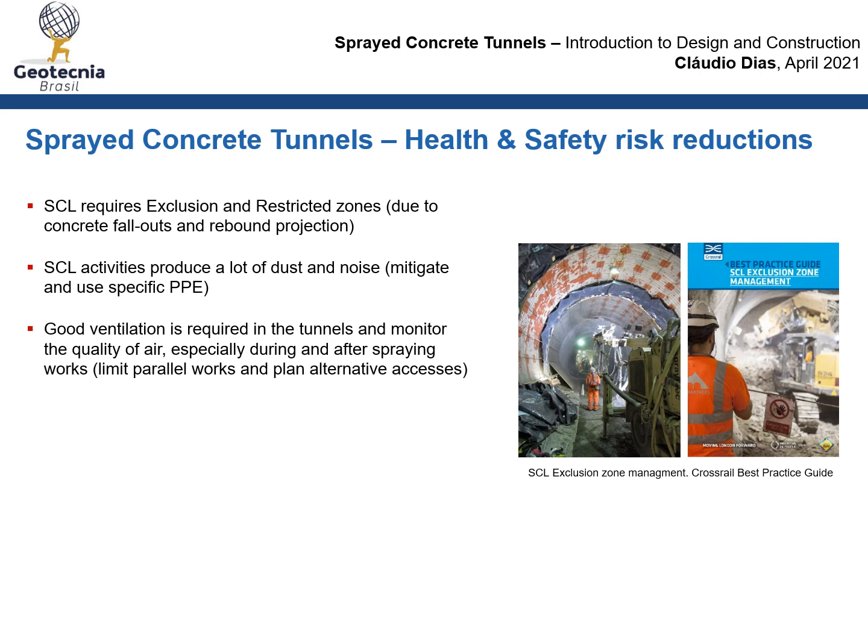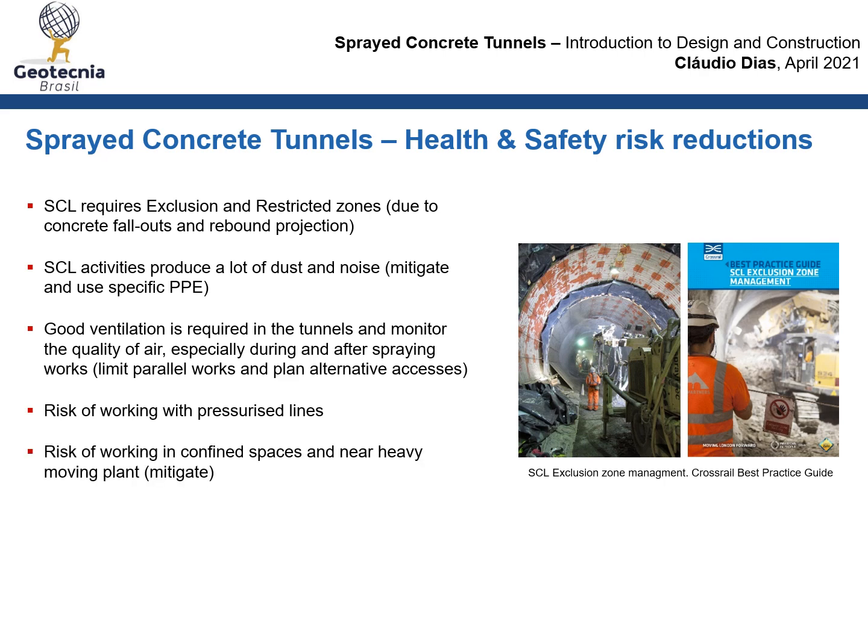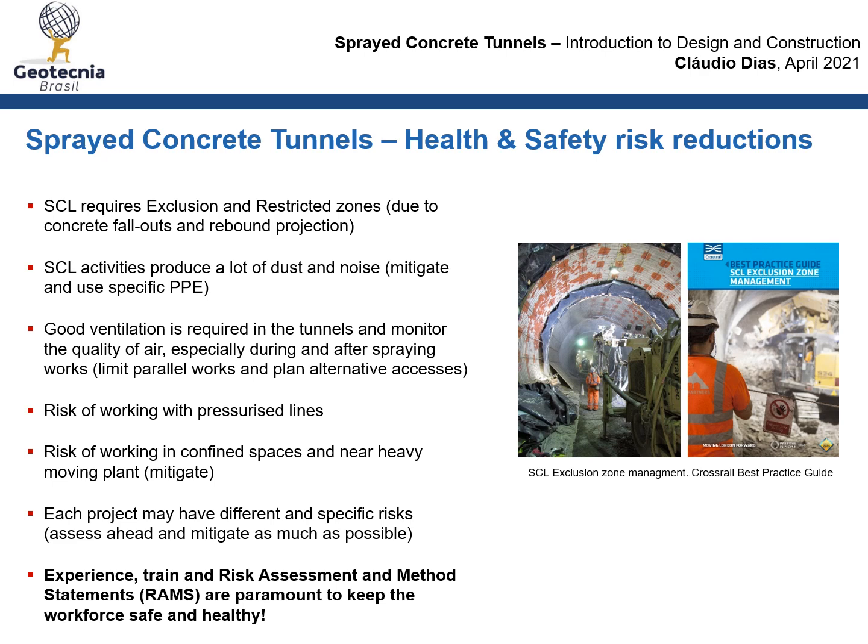Good ventilation must be provided, especially during the spraying works and after it. There is the risk of working with pressurized lines, risk of working in confined space and near heavy moving plant. As every project is different, it's very important to assess the risks ahead and plan and mitigate the risks as much as possible. Ultimately, the experience, training, and risk assessment and method statements are paramount to keep the workforce safe and healthy in a tunnel project.